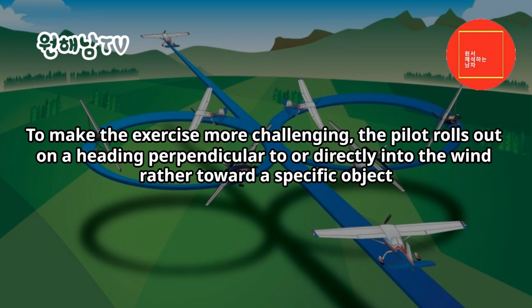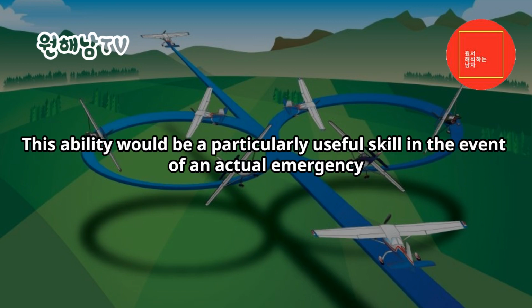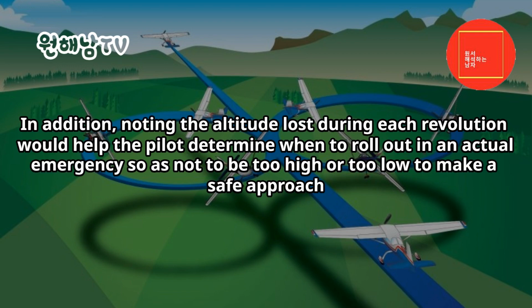To make the exercise more challenging, the pilot rolls out on a heading perpendicular to or directly into the wind rather than toward a specific object. This ability would be a particularly useful skill in the event of an actual emergency. In addition, noting the altitude lost during each revolution would help the pilot determine when to roll out in an actual emergency, so as not to be too high or too low to make a safe approach.